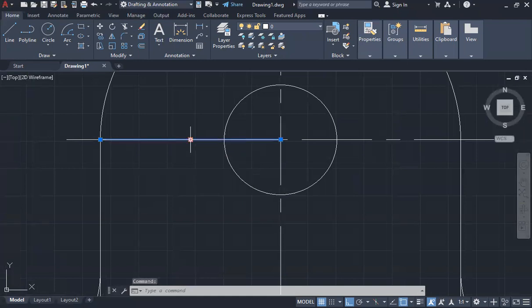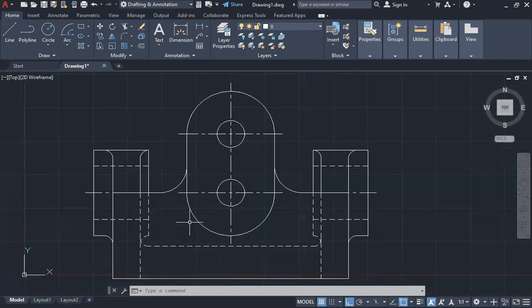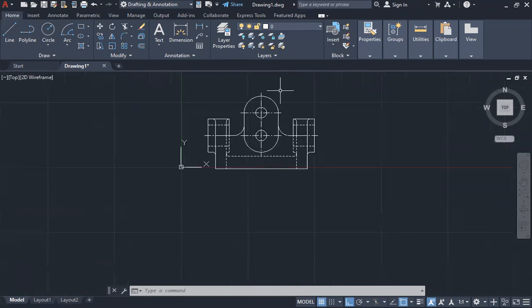All right. Now, if I did the overkill command from last week before I changed my line type, then that would have sorted it. But my approach this week was I deleted all of them manually as I was drawing, and then that way I don't have that problem later when I change my line types. So I've done this bit now.